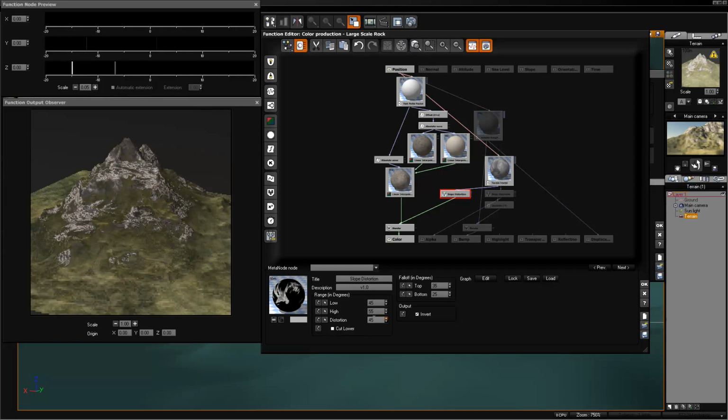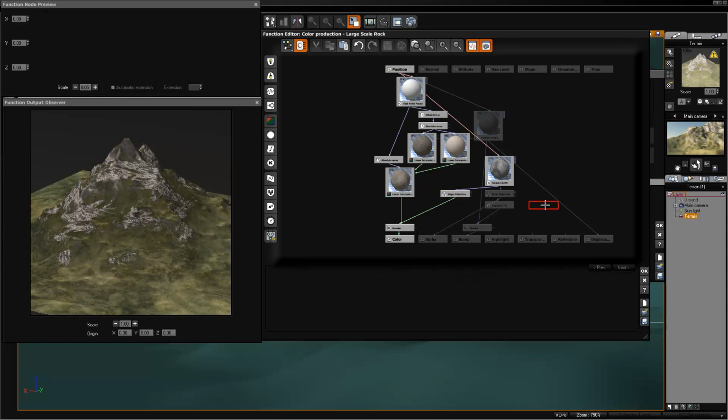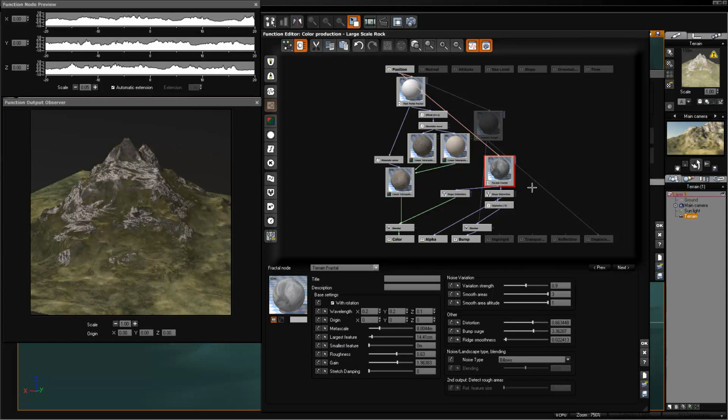Also keeping in mind you can control the distortion with another fractal to have the distortion amount vary. So that is kind of cool. But you will need to map it to fall within a certain distortion range. If you're not quite sure what I'm talking about, basically the output of this terrain fractal is 1 to -1. In this case, it's really more cutting off at 0. It doesn't really fall below 0 much.